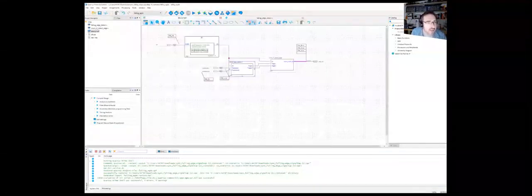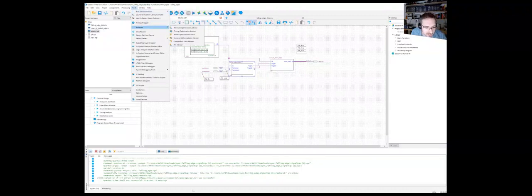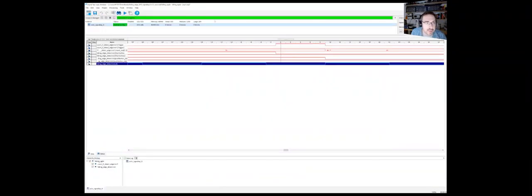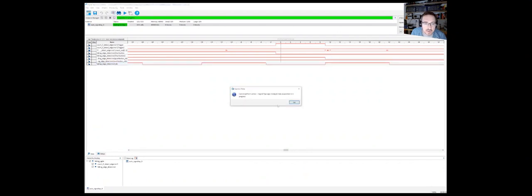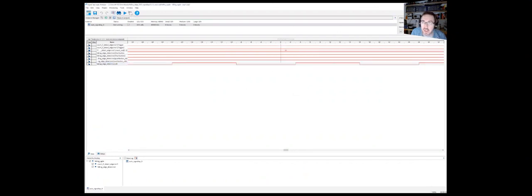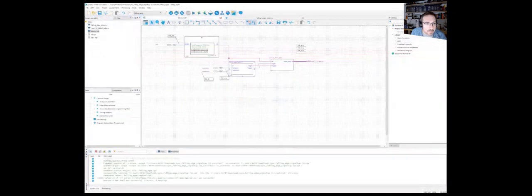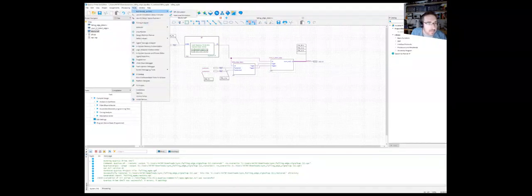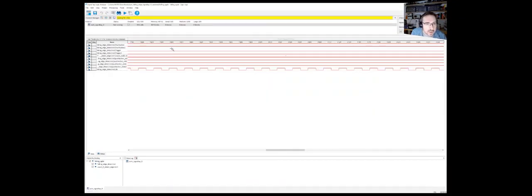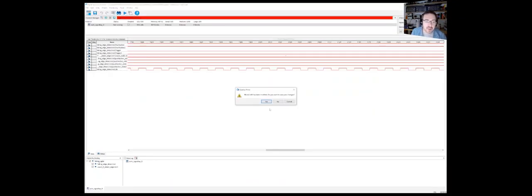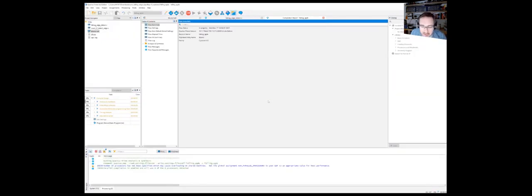So what we're going to do is open Signal Tap. I think it would make sense if I close Signal Tap from the previous design. So you have to stop it and then close Signal Tap, and then is this the new one? Yeah, okay, so let's just tidy that up a little bit. So let's open Signal Tap. It's Tools, Signal Tap Logic Analyzer. And again, we have to run compilation, unfortunately, because it's an unarchived project and that requires a new compilation.